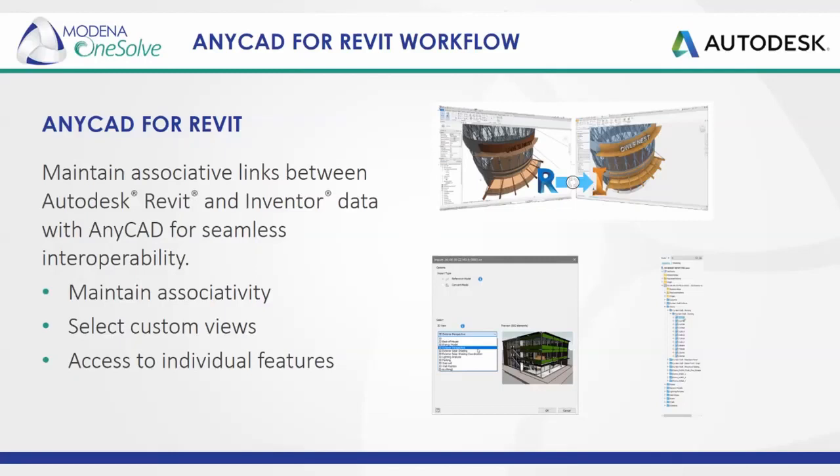AnyCAD for Revit allows for an associative link to be maintained between Revit and Inventor data. How does AnyCAD for Revit work? Inventor can access data from a Revit project, either from a local file location or a cloud storage location provided by BIM 360. A Revit model referenced into your Inventor assembly will update as changes are made to the Revit project. Let's take a closer look at how this AnyCAD for Revit workflow operates.